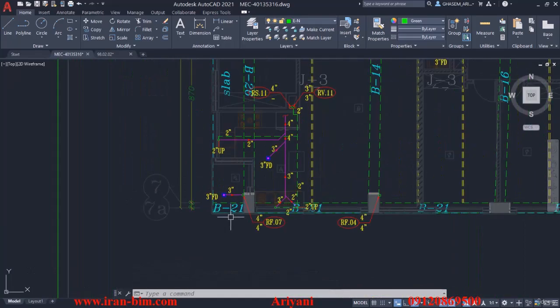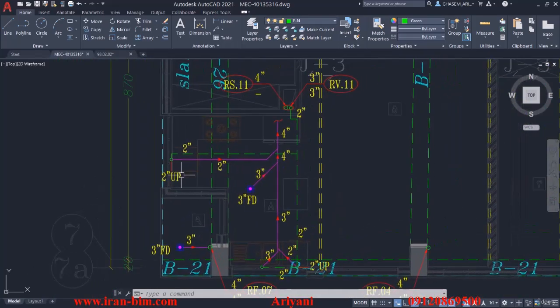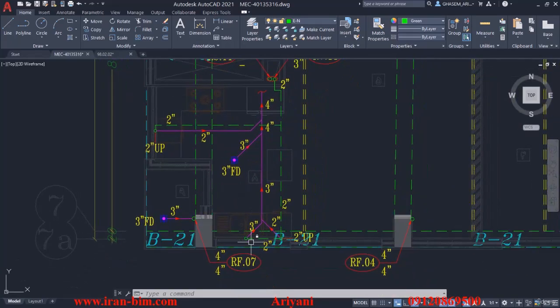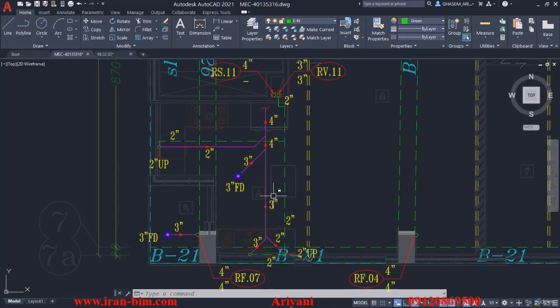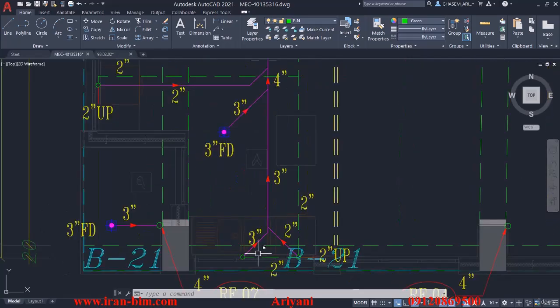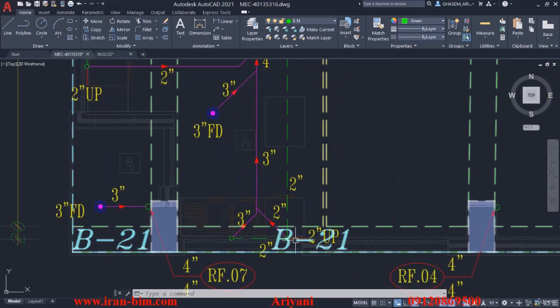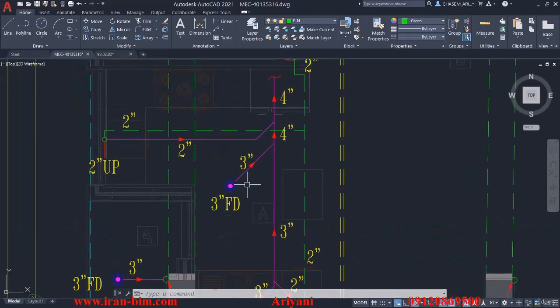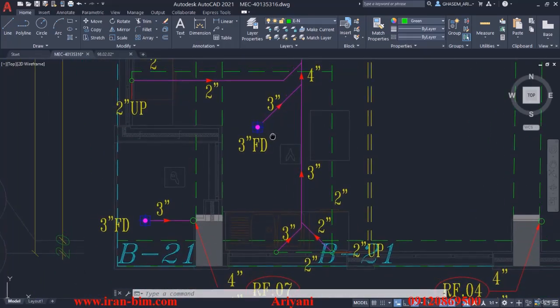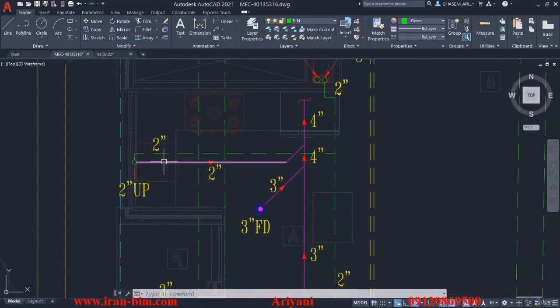So now we can find our critical points in the plan. For example, we'll say we have a beam here, so it's a critical point. This is just the flooring for the kitchen. We have 2 sinks over here, then we have a vent that goes up and it needs to be under the beam. And then the sewage here goes under the beam as well because of the sinks here, one of which goes from up to down. And then we have the floor drain here as well.